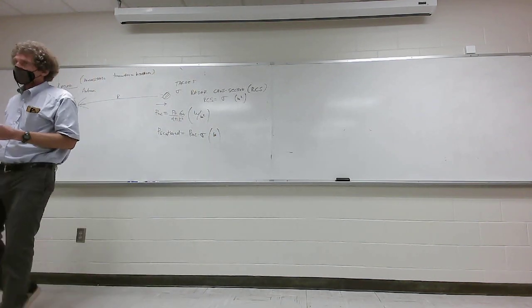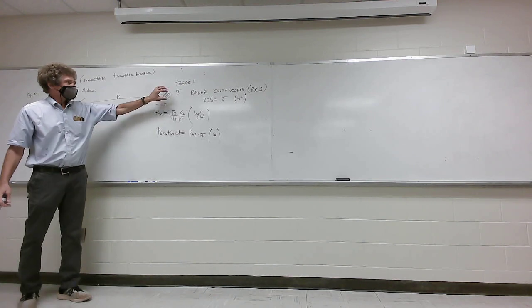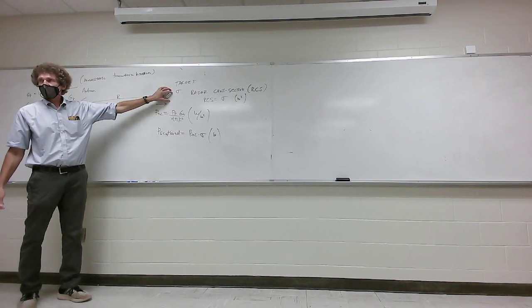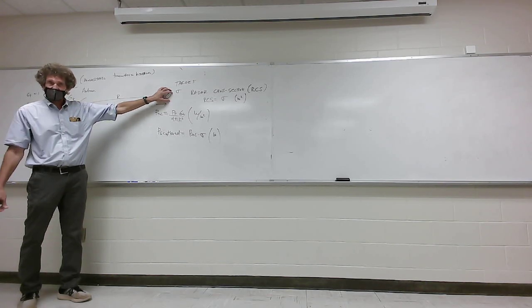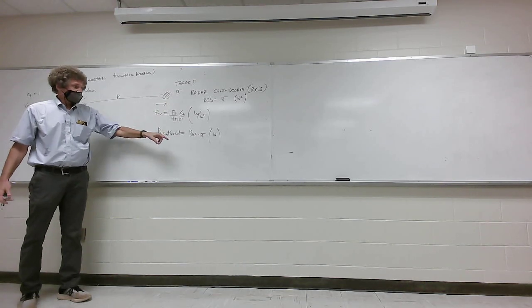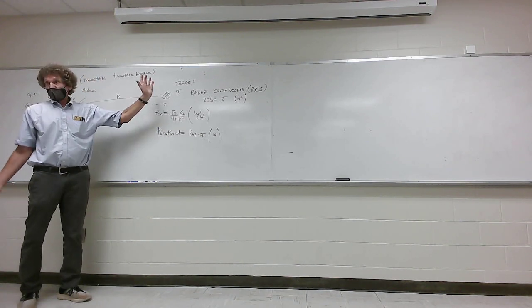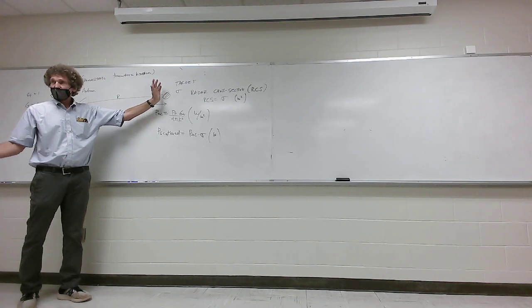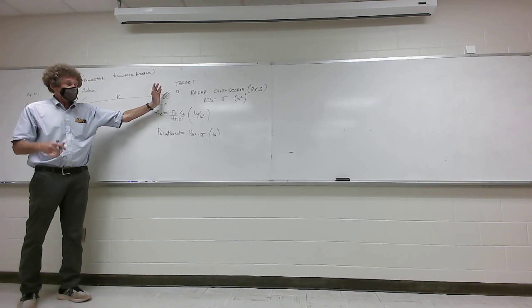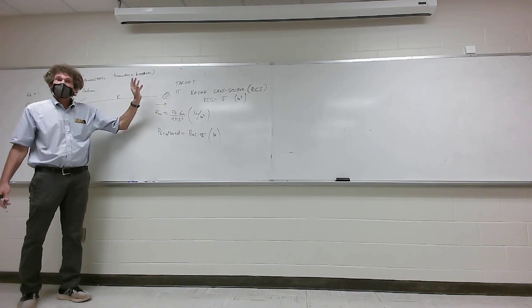So now, once it hits and reflects, this looks like a transmitter. Y'all follow me? It itself looks like it's re-radiating the signal. And how much of the signal? This much. Y'all with me? Can y'all follow that? All right. So the signal comes, so much of the signal paints the target, I use the word paint because it's common. It hits it, I multiply the power density by the radar cross-section, I find the amount of power reflected.